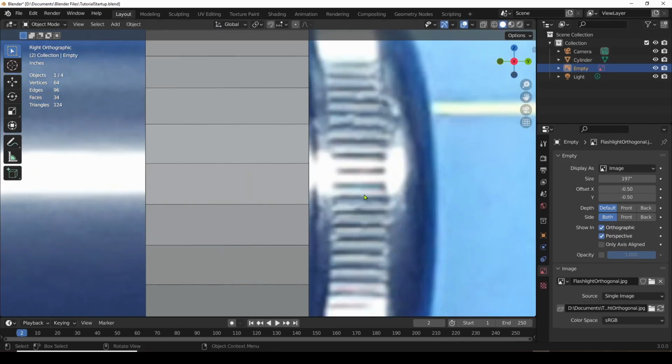We'll zoom in here, and you can see somehow we're going to model this flat face and then an indentation and a flat face, an indentation, a flat face, and so on all the way around. But if you look at our cylinder, we've got one face, this one polygon. Somehow we're going to have 1, 2, 3, 4, 5, 6 polygons inside here, and we're going to extrude every other one. So it turns out we made a big mistake by just adding the cylinder the way it is.